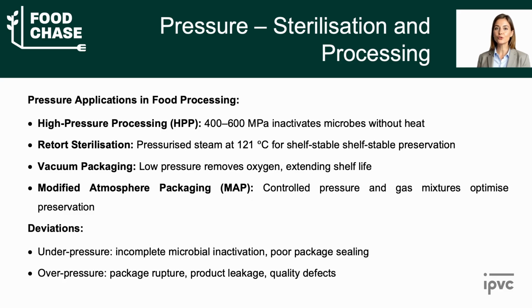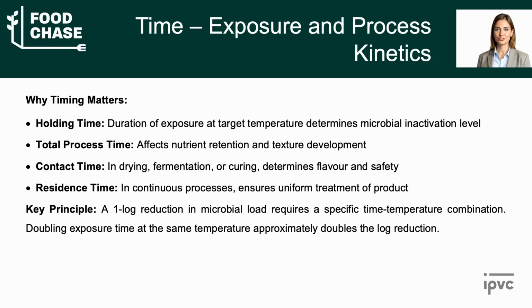If pressure is too low, protection is inadequate. If it is too high, packages can rupture or products can be squeezed out. So precise pressure control is essential. Time is perhaps the most misunderstood parameter, but it is absolutely critical. Microbial inactivation is not instantaneous. It follows kinetic laws. We describe this in terms of log reductions.